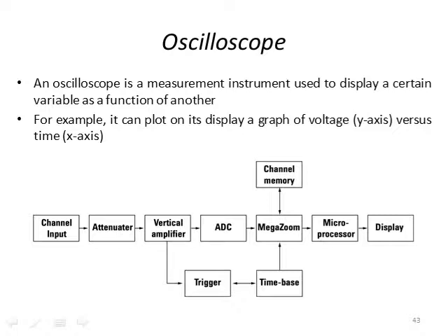And one of the most important aspects of doing a good measurement is paying attention to how you introduce the signal into the oscilloscope. And this is the channel input, where we actually have a probe, a coax cable that we plug into the front of the oscilloscope, and then we want to clamp it to our circuit.